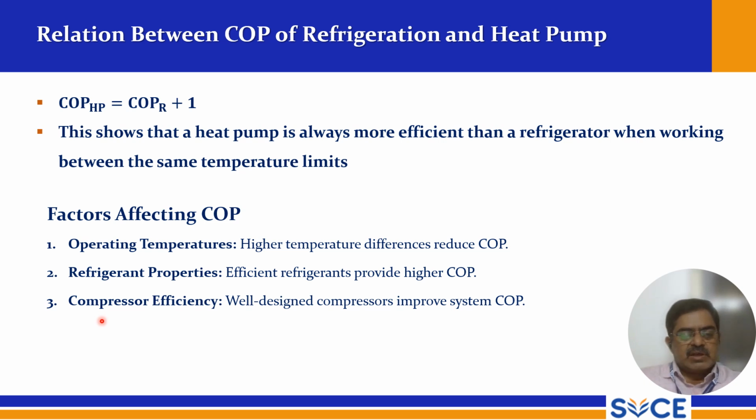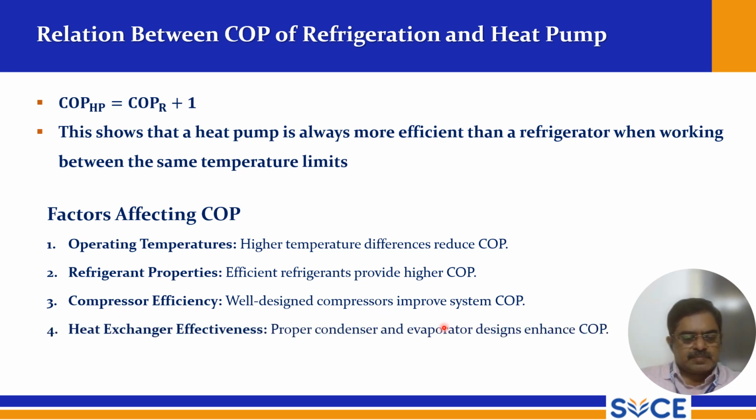Compressor efficiency. Compressor is one of the major component of a refrigeration system. Well designed compressors improve system COP. Heat exchanger effectiveness. The proper condenser and evaporator design enhances COP. Definitely a proper condenser and evaporator is required to enhance COP or to achieve more COP.